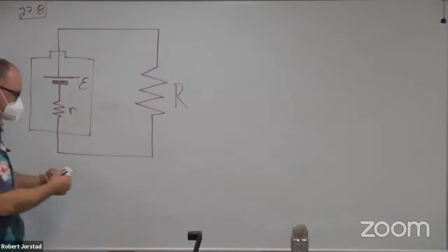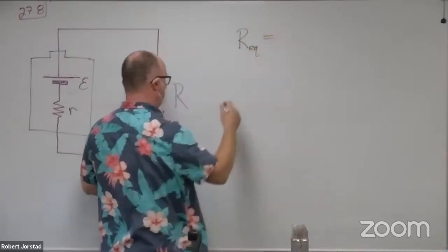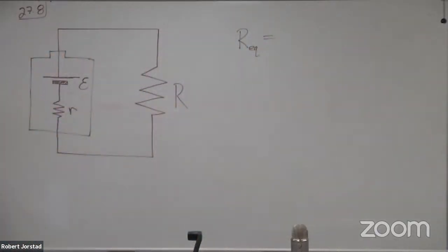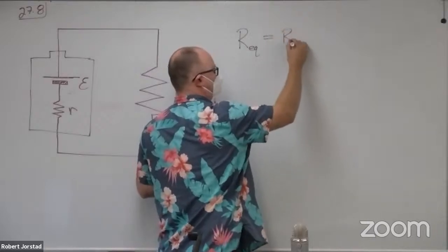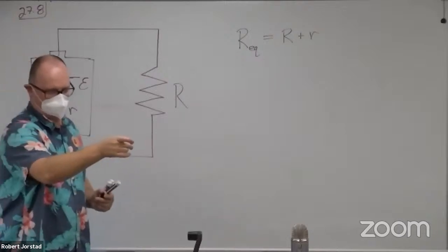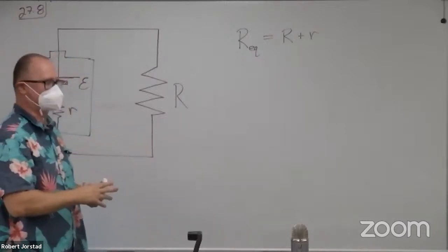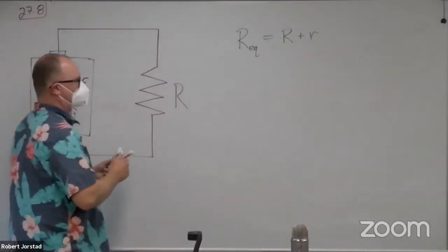Now, in this case, what's the total resistance? If you have two resistors in series, how do I get the equivalent resistance? What's that? Nope. Add them up. Remember, capacitors would be the one over in series. Resistors, you just add them up. So resistors in series, that's like making them longer. L is in the numerator, rho L over A, just add them up. All right. In this case, what would the current be?